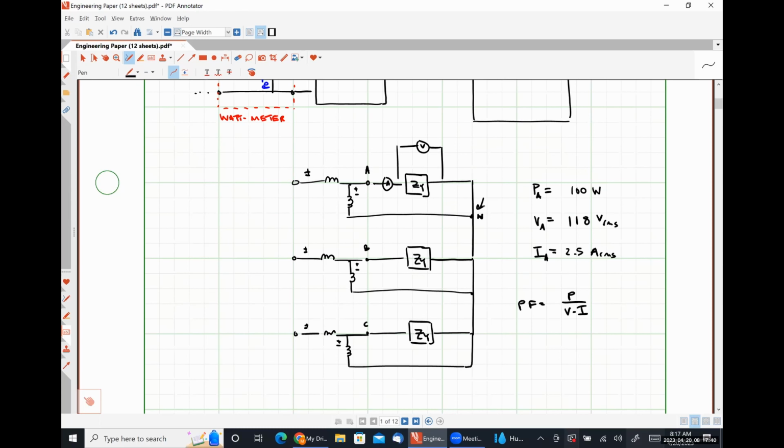So for instance, in a 3-phase induction motor, we are only going to have access to the line terminals A, B, and C. The neutral point where all things are connected together is literally internal to the machine, and you probably don't want to have to take the whole thing apart to connect a meter there and then put it back together and run it and hope that everything is okay. It'd be vastly expensive and complicated to do that.